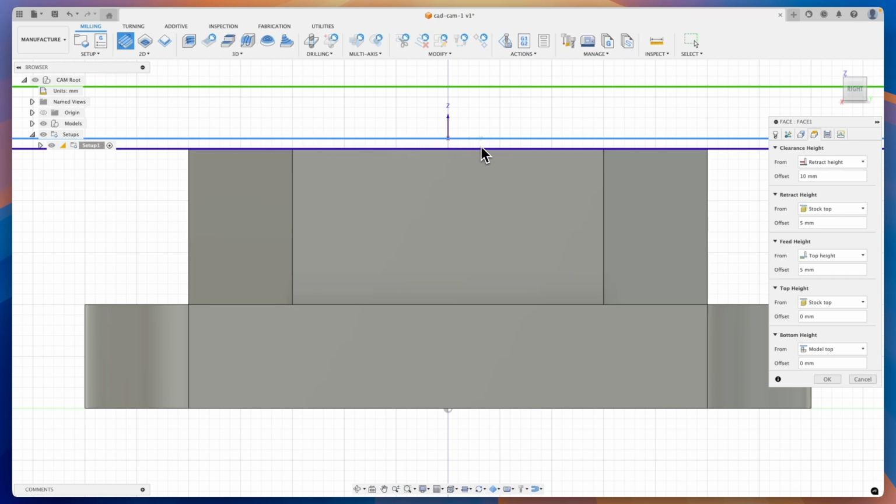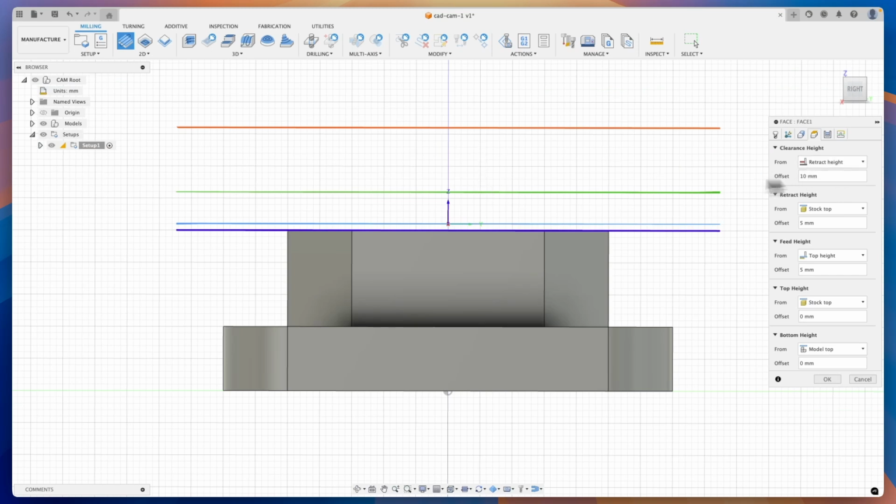That's why I mentioned earlier that we don't have to worry about those levels, because they are above the top machining level, so if the tool moves in rapid move, in the case of machining such a single part, we don't have a risk of collision. So we can leave such values at these levels and move on to the next tab, the Passes tab.